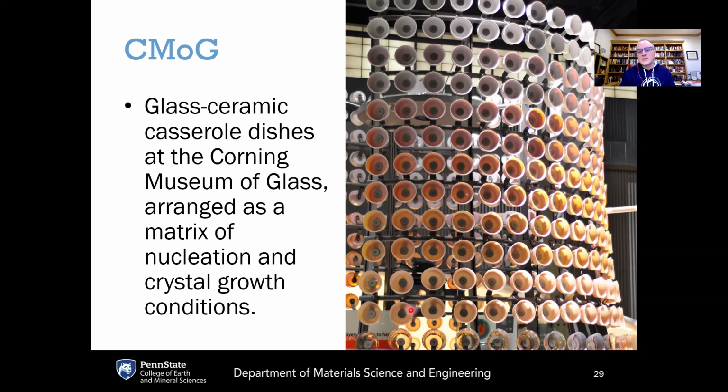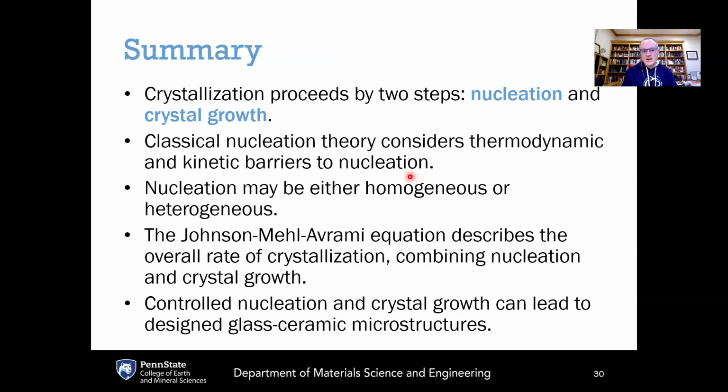And as you increase the amount of crystal growth time, you go up here, and this transparent cookware becomes translucent and eventually becomes opaque. The white one that you show here has larger crystals, and that was commercialized as Corningware. And you can see here as you're continuously changing that, how this continuously changing crystal microstructure is affecting the optical properties.